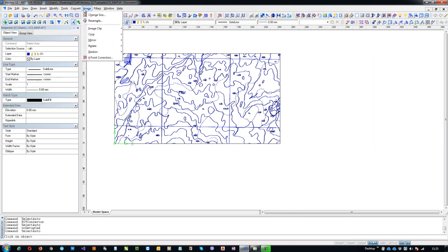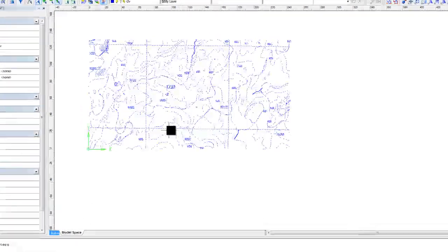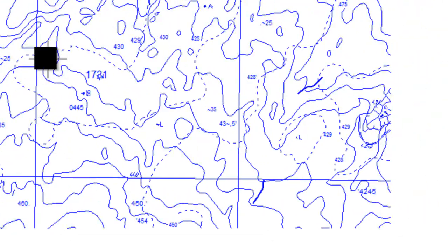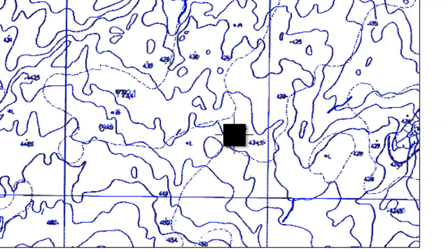Once you set the options, then you can always go to vector autocorrections. So after conversions, you basically need to select the vectors you have. So I select things and I say vector autocorrect. What it does, it actually corrects a lot of things in the converted vector. Then you can save the converted result into DWG or DXF, right? So it will eliminate most of the problems in the converted results.